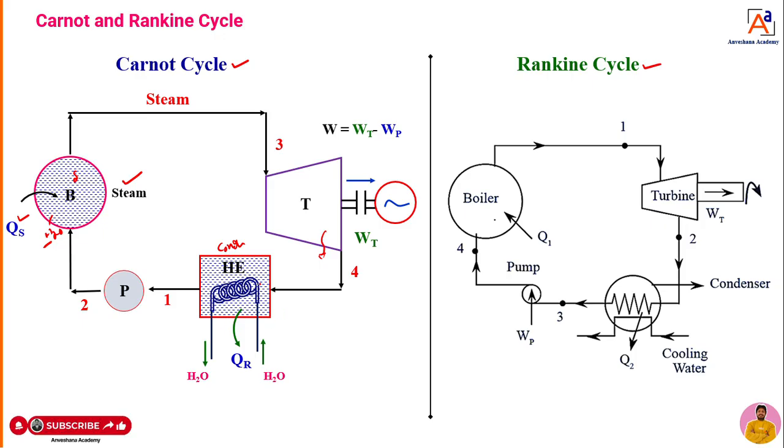That steam is going to convert into water again with the help of a cooling medium. In the condenser, we are going to convert steam into water. Again, with the help of a pump, we are going to pump that water to the boiler. That means initially it was water, finally it is going to reach water itself. You can take a certain quantity of water and assume it as a system. That means it completes a cycle.